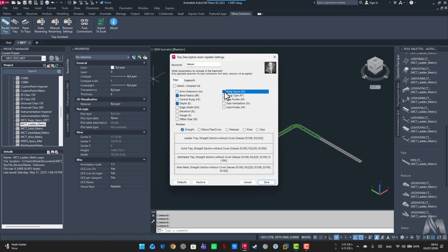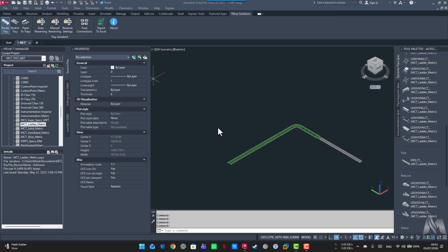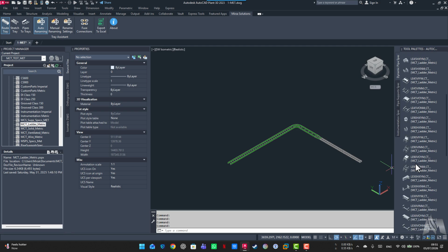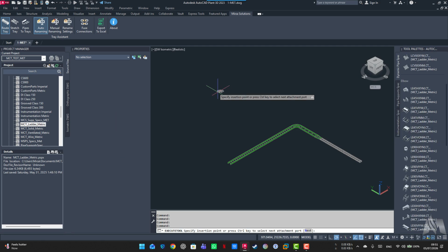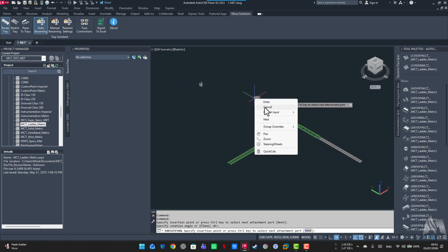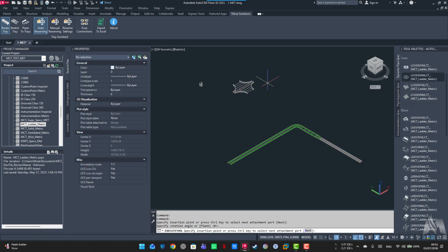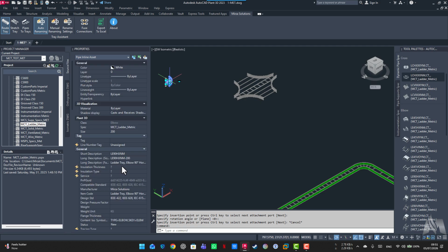And if we have an automatic system like the cable tray routing, this would be very good. So let's click on the auto renaming. It is also a toggle button. And now if I place any component, say for example this elbow, and for example this cross, and we go over here, we click on it, and you see the name is already there.